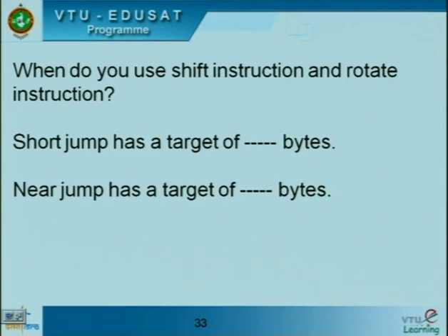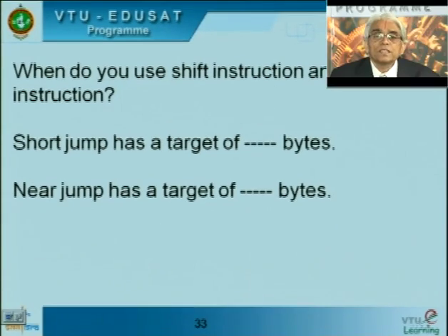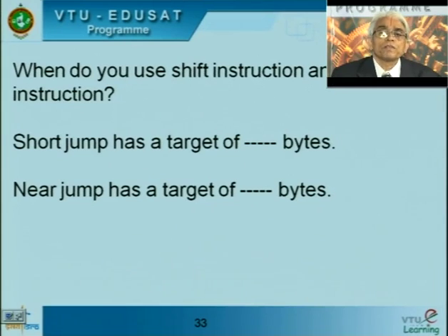Now, you should know the difference between these two. Shift does not allow you to make the least significant bit come back to the most significant bit, or bring the most significant bit to the least significant bit. Either way it is not possible, whereas in the case of the rotate instruction, that is the most important part. So, no data is being lost. It can be through carry or it can be without carry.